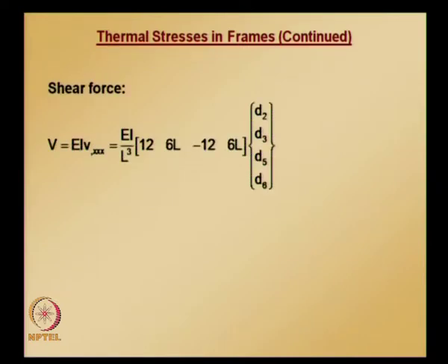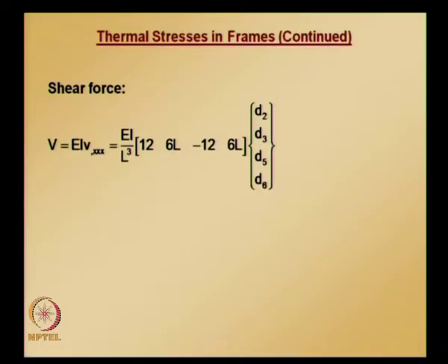As I mentioned, because of thermal effects only bending moment and axial forces will be developed, which are going to be uniform or constant over the span of the element. No shear forces will be induced, so there is no fixed end shear correction when you are calculating shear force.